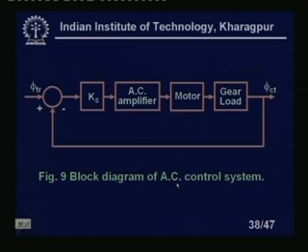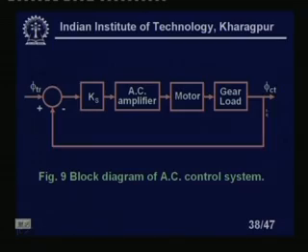This is our block diagram of AC control systems. We have phi TR, this is our command, right. I want this particular position, I am getting phi CT. Our goal is phi CT should be exactly equal to phi TR. So, if there is a mismatch, this is coming as an error. If there is no error, phi TR minus phi CT will be 0. If there is an error, a non-zero voltage will come down here.